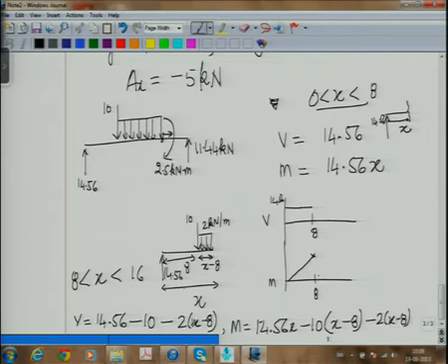Now where is this force acting? It is acting at half of this, and we have to look at the distance from the cut section, not from the start. Please, in this case it doesn't matter, but we have to look at this section to half of this. What is half of this? X minus 8 divided by 2. So that means what we have to multiply here is with an x minus 8 divided by 2. So let me, I think I'll write this on the next page.